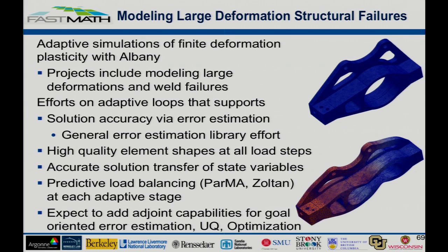And then there are areas where we have a lot of things going on, where the mesh is adapted pretty nicely in here. So we need to do this in parallel, and do it so that we keep basically the same amount of workload on each MPI process. This requires load balancing as the calculation proceeds. Basically, every few load steps of the calculation, we determine if adaptation is necessary, perform that step, and then load balance right at the adaptation step.